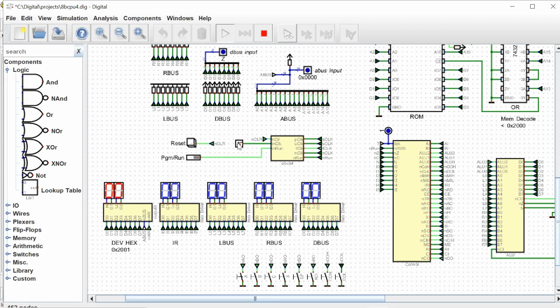And that's low clock again. All right, now we're at step 2. We've moved the program counter to the memory address register, which has 0. Now we're going to read that RAM.